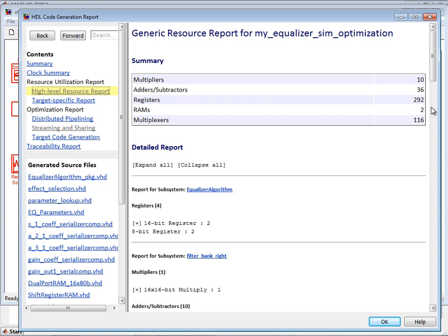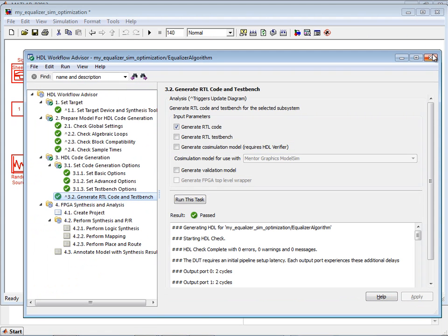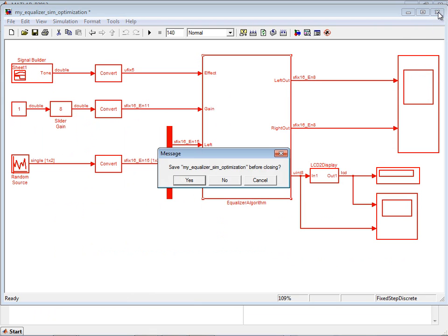And you can also see that some of the large integer delays which have been introduced we were able to map to RAM blocks. Again, whether this happens or not is configurable, but in this case the model has been configured to map those parts of my system also to block RAM. So let's go back to the PowerPoint presentation.